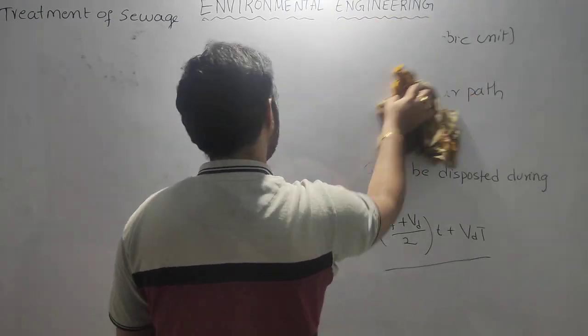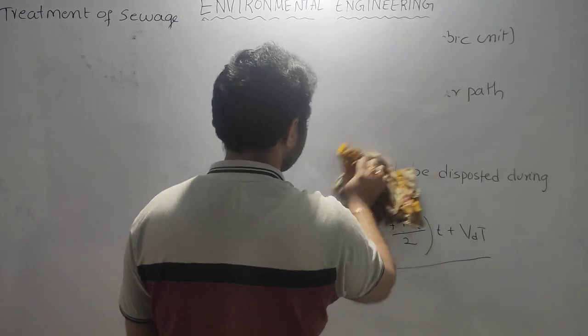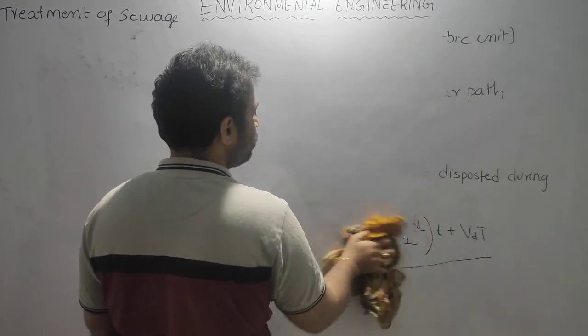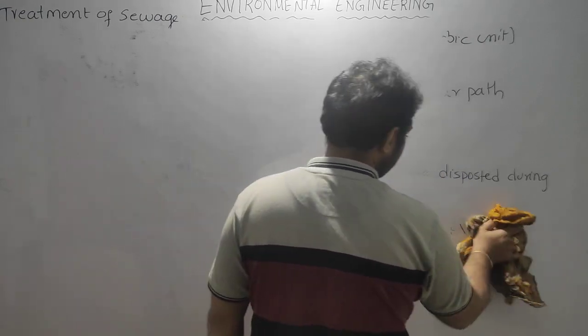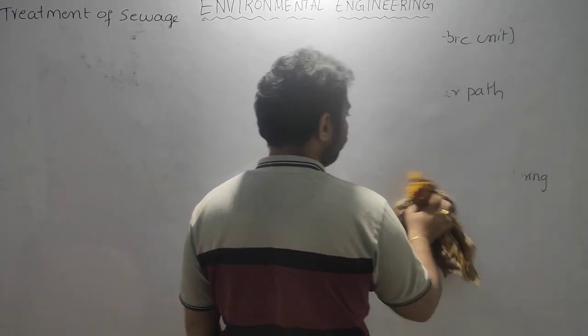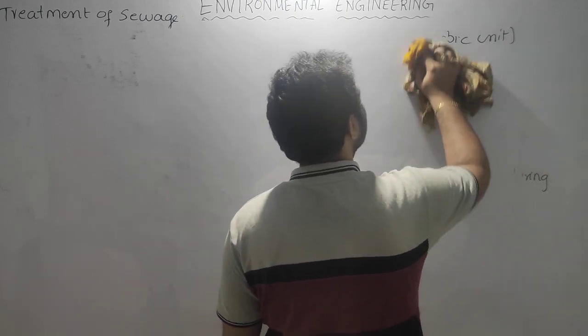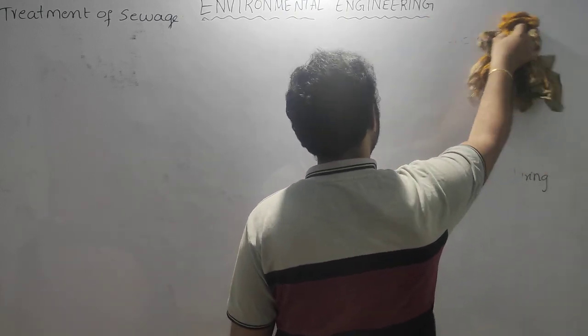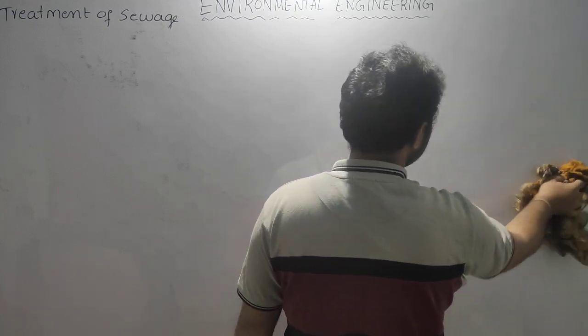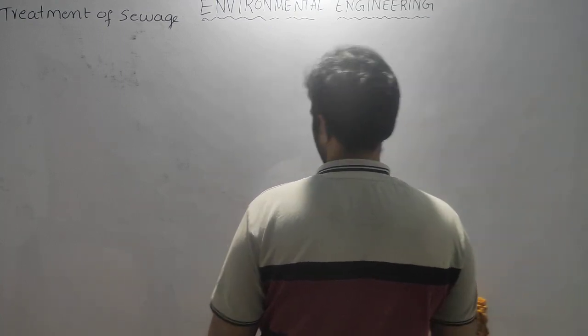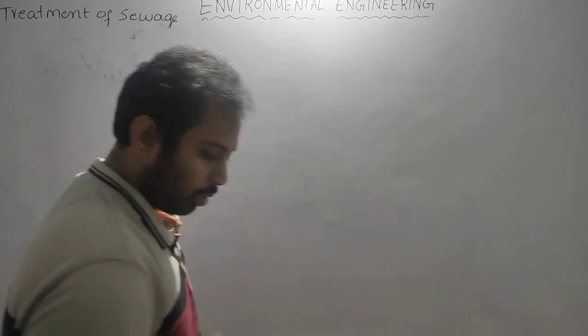That role is taken care of by the sedimentation part, the settling zone inside the septic tank. When the settling is over, the sludge is settled deep into the septic tank. There it will undergo anaerobic digestion, because there won't be any free oxygen available in the septic tank. It is completely closed.